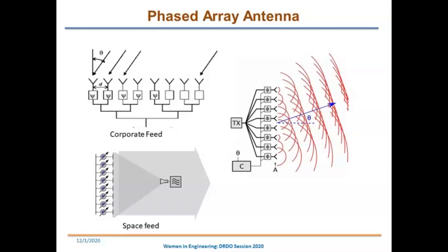For example, if you consider the Fourier transform of a square function, we have a sinc pattern. Here also, if you consider the antenna and that sinc function, you can see the side lobe level you get is around 13.5 dB. Whatever amplitude you apply here, if it is equally weighted, then it is flat, like a square. When you transform it, our antenna is a spatial filter. In digital it may be a time domain filter, but here we consider the antenna as a spatial filter.